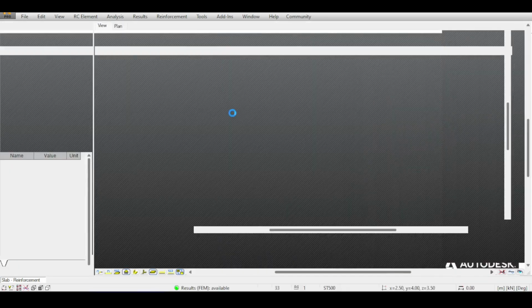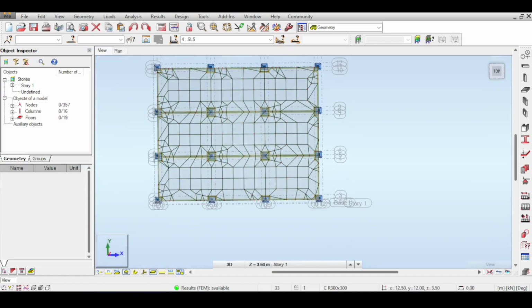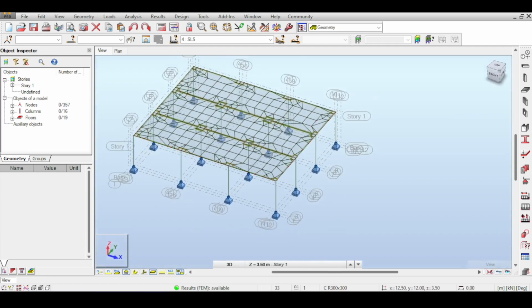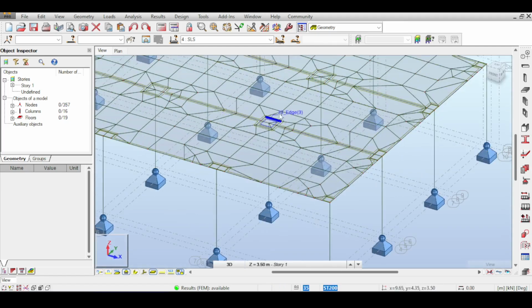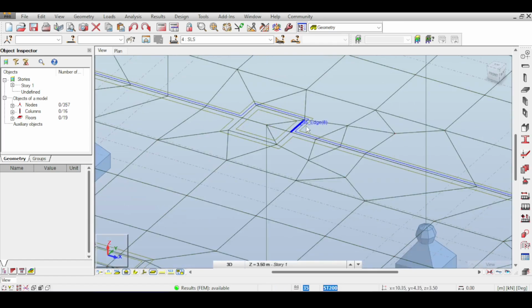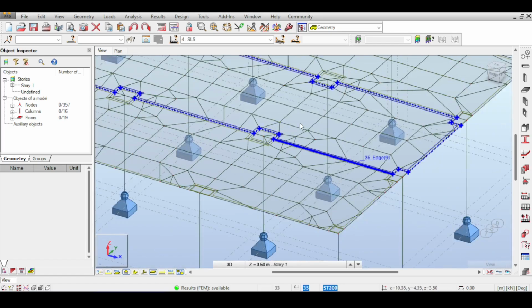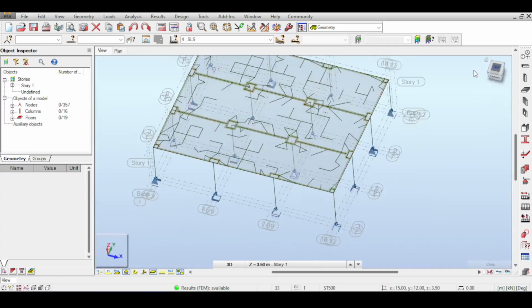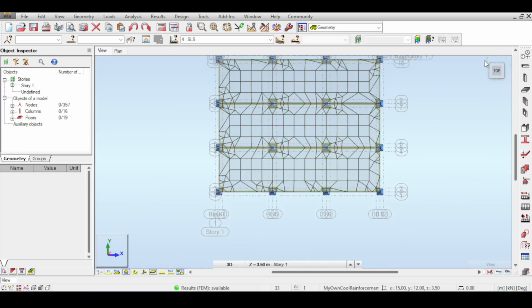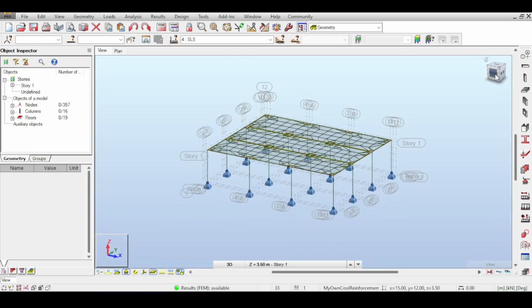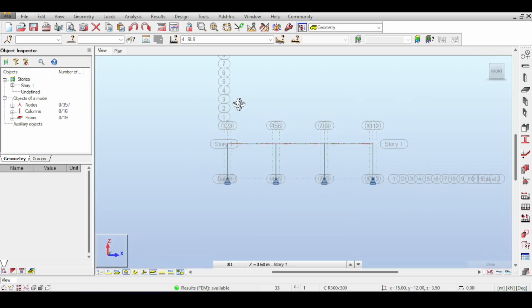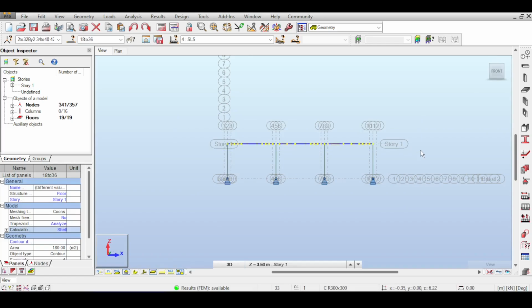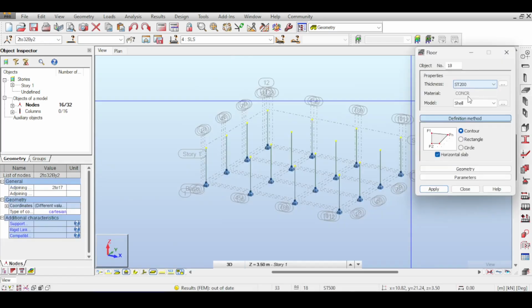Now, how can I fix that? Robot faces a problem in the analysis and design of those drop panels because they are too small. Like 700 by 700 is not a valid drop panel. So you could increase the drop panel to make it work. Option number 2 is actually an easier and more practical option that I will suggest right now because of the limitations of the software. And I'm not making this up. This is what I would really do. I would just basically go back to my single slab approach, thickness 200, shell.